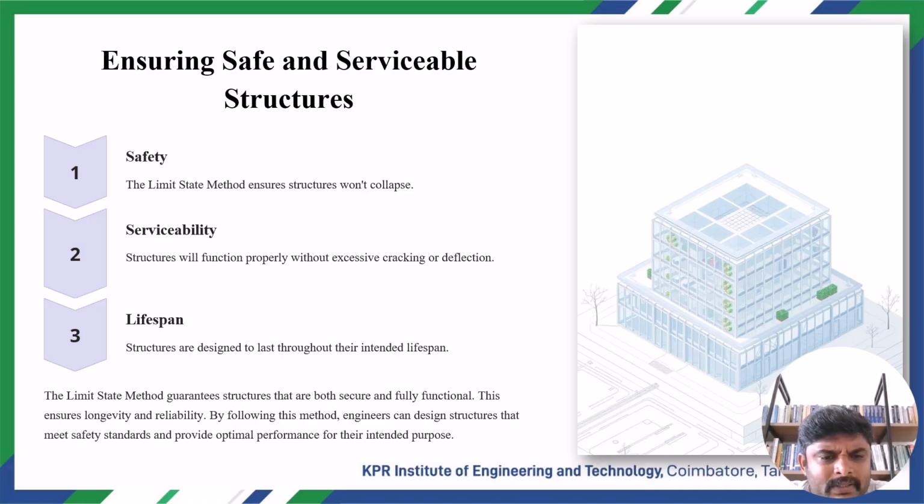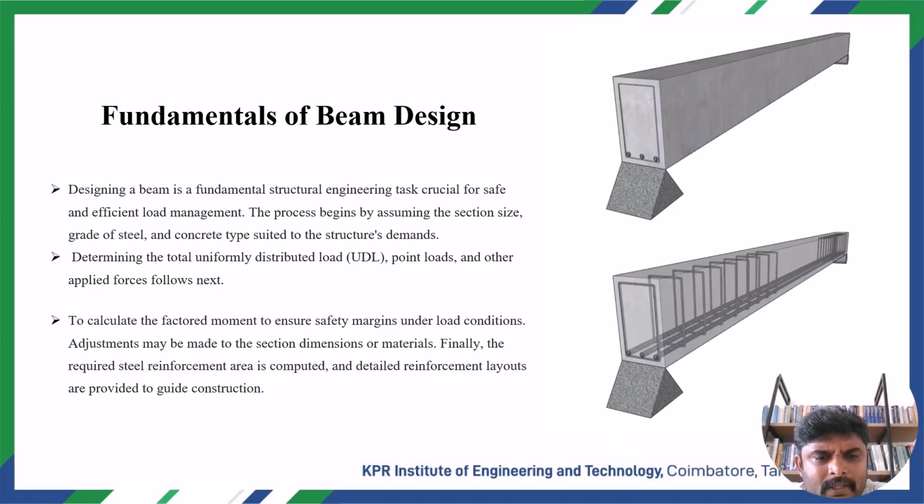And then, to ensure safety and serviceability. Safety means the limit state method ensures the safety of the structures without any collapse. And serviceability means without excessive cracking and deflections. A structure is designed throughout its lifespan. For example, if you design for 50 years, the structure should be stable for 50 years. There is safety and serviceability.